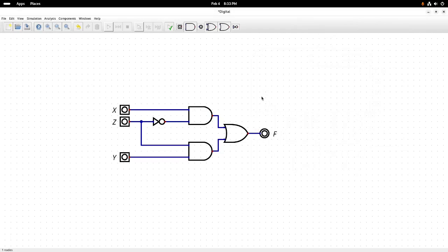But nothing here is really indicating that this has a static hazard glitch. If we do maximum path length, it says the longest path has 3 gates, but it doesn't warn you that all the others do not have 3. And even if we do a simulation, it's going to show that everything's fine, nothing's really wrong.